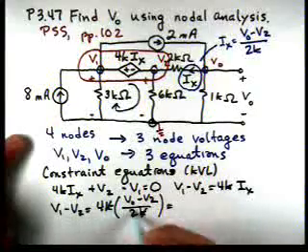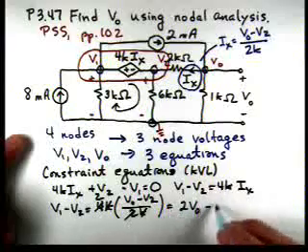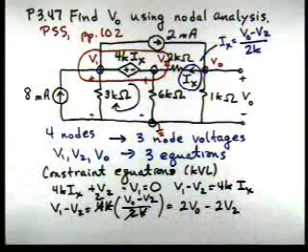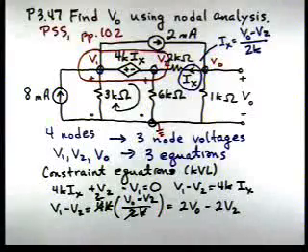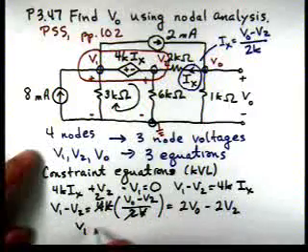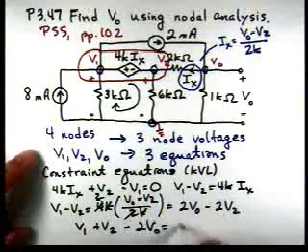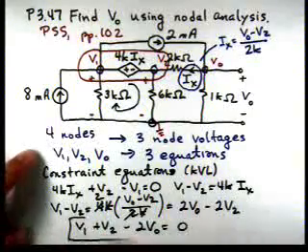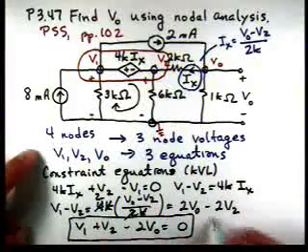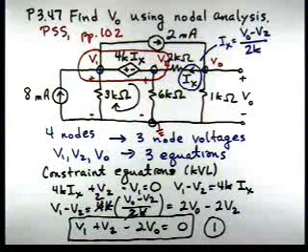So we have V1 minus V2 is 4K times V0 minus V2 over 2K. And the K's canceling, we're left with a 2. So we have 2V0 minus 2V2. Now, let's move everything on the right hand side over to the left hand side. And when we do that, we'll have V1 plus V2 minus 2V0 equal to 0. Okay, there's the first of our 3 equations, and that comes from the constraint equation.